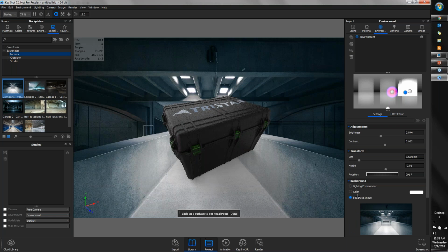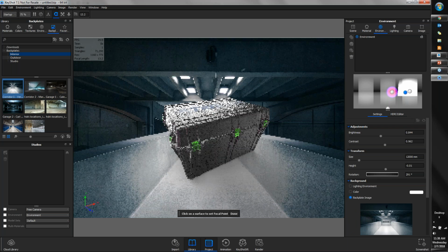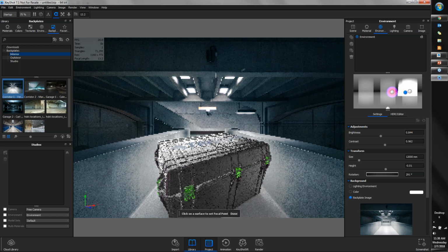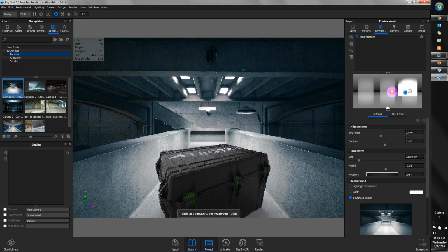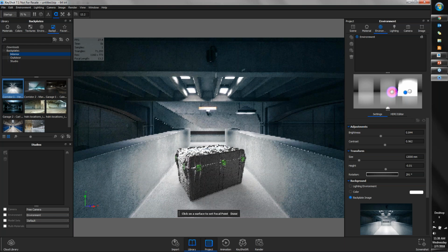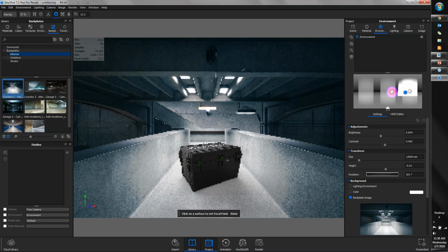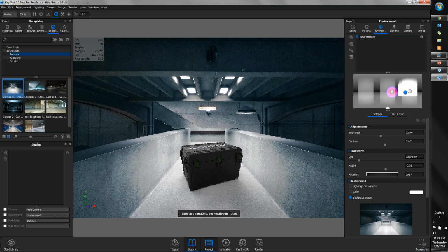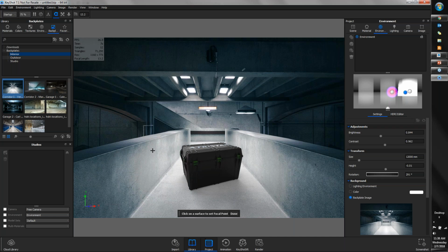and drop a backplate in here. And you can see now we're going to be positioning our model on that two-dimensional backplate. So if we want to match a specific backplate, we can always do that using our camera settings and select that backplate, select references, maybe these different lines, and create a three-dimensional model that's going to match the angles and focal points of that specific backplate.